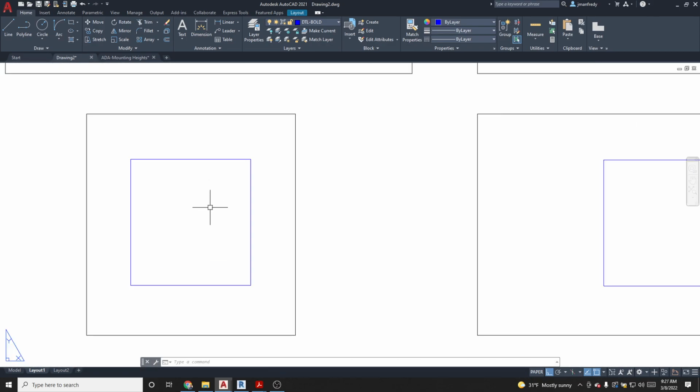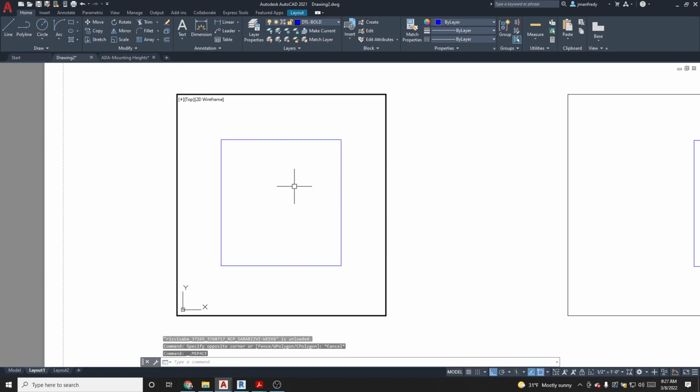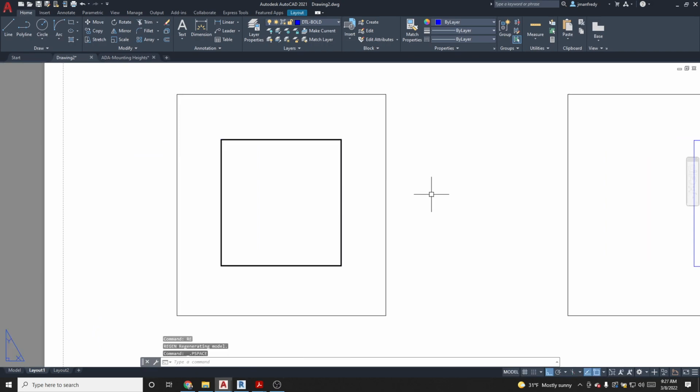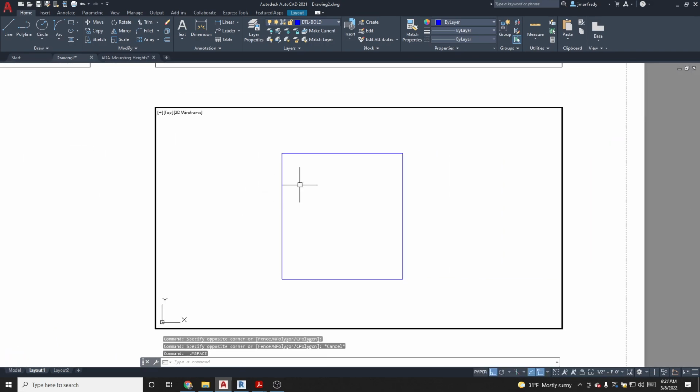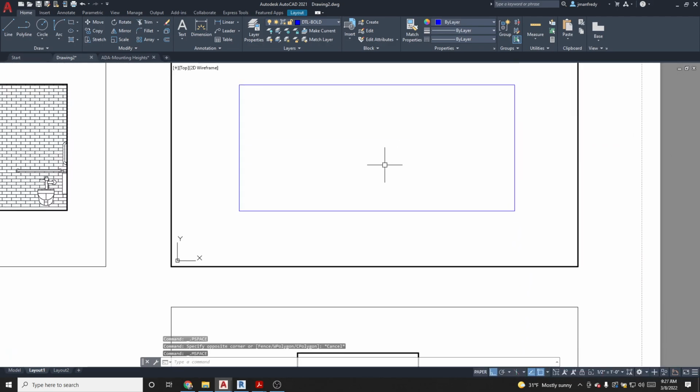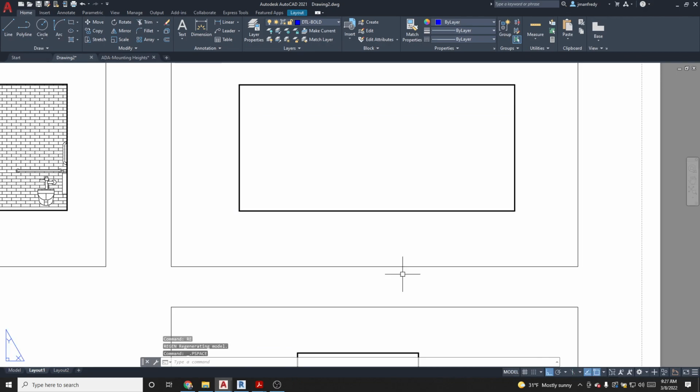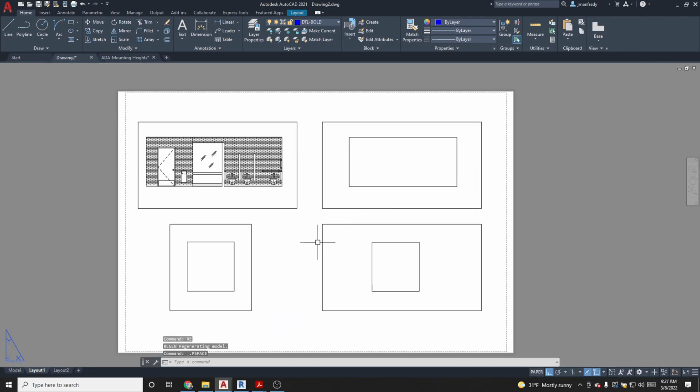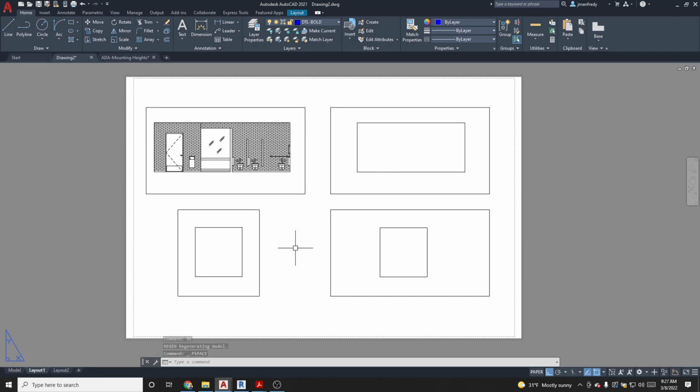You have to activate the line weights inside here. Double click, type RE, line weights are activated. Double click, RE, activated. Double click in here, RE, activated. One window per elevation. That's all this drawing is doing. These guys are on the depth points layer. They will not print. The drawings will print. These boxes will not.